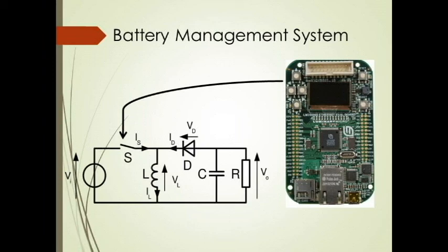Solar panels are connected to the input of the buck-boost converter. The converter bucks the voltage if given a duty ratio less than 0.5, else it boosts the input voltage. Duty ratio of the control pulse is triggered using a microcontroller.